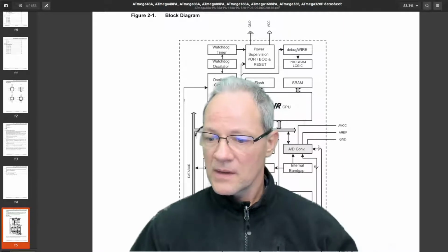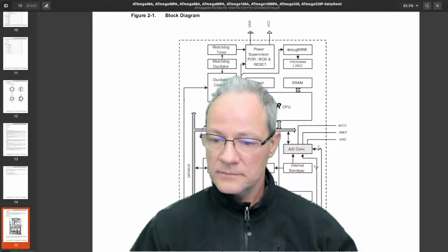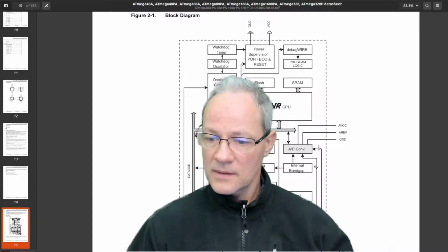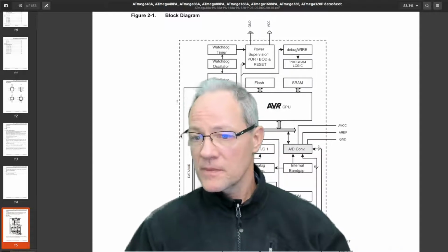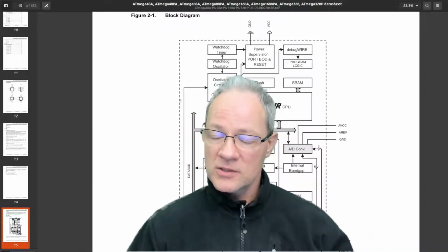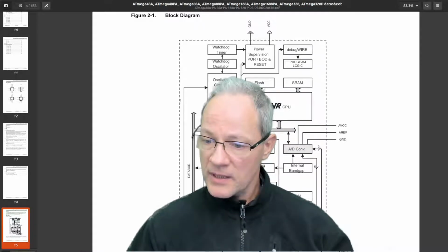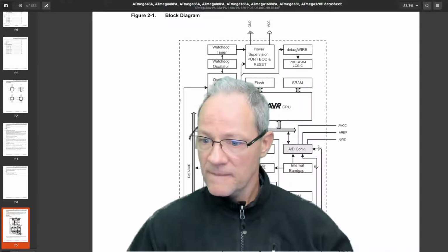All right? And these ports can be configured as general purpose input-output ports, driving the LEDs or simple things, or they can be connected to other devices, as we can see through these lines that go up here, for example, to the analog comparator here.